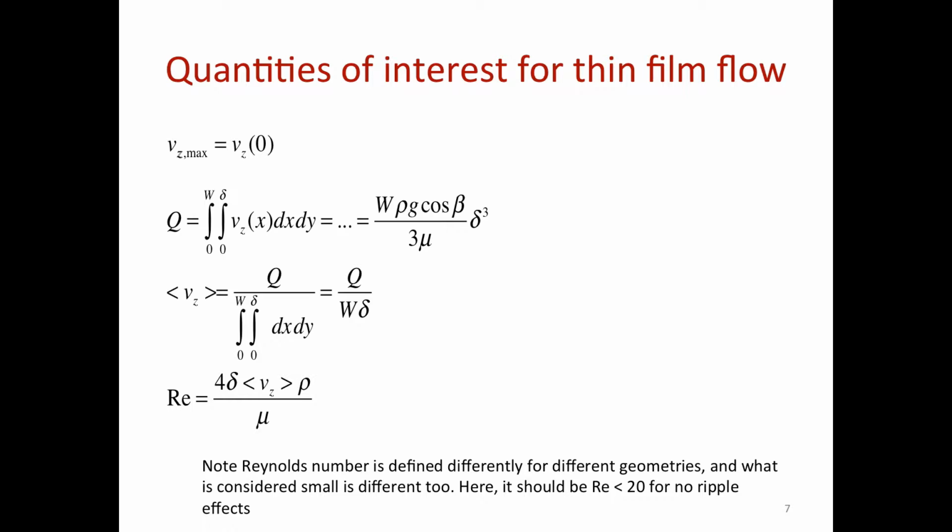So any absolute value of Reynolds number you can always take with a grain of salt. What matters is the order of magnitude. Times 2, times 3, times 4, that's not all that important. What's important is the order of magnitude, because there are certain choices that you can make. You have to look them up in the literature to see what people have traditionally been taking for what type of flow. In this type, they were taking 4. I'm pretty sure, though I didn't look it up, that for some normalization in the past, it made sense to put 4 in there, so that something is normalized or equal to 1.